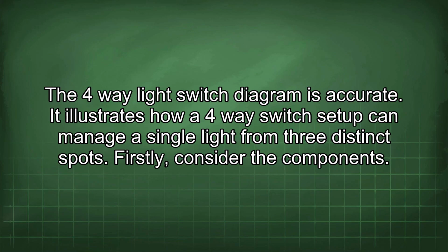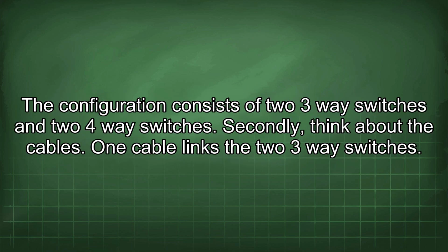The four-way light switch diagram is accurate. It illustrates how a four-way switch setup can manage a single light from three distinct spots. Firstly, consider the components. The configuration consists of two three-way switches and two four-way switches.